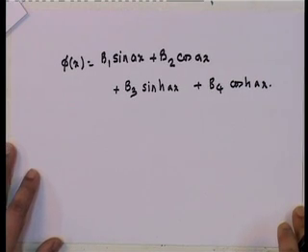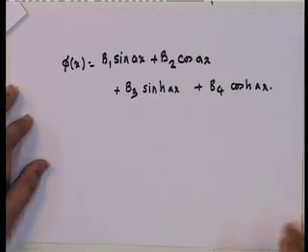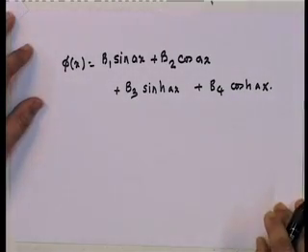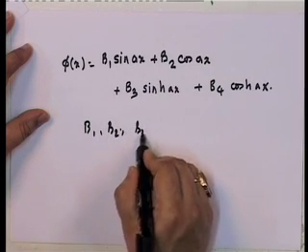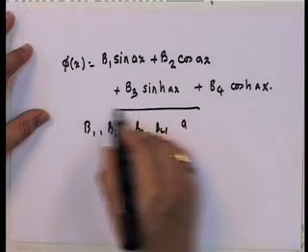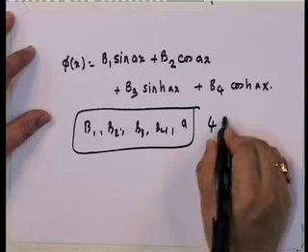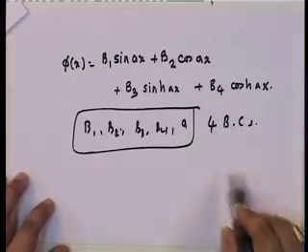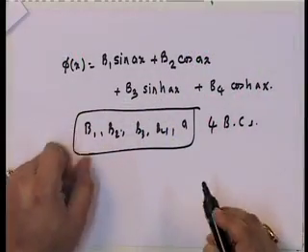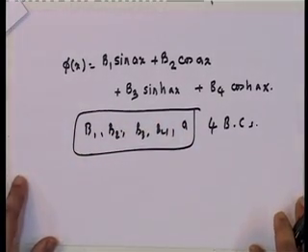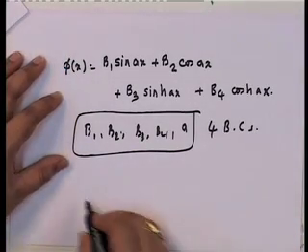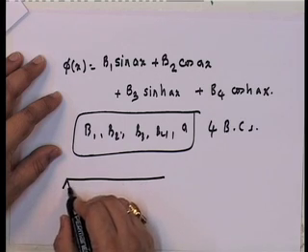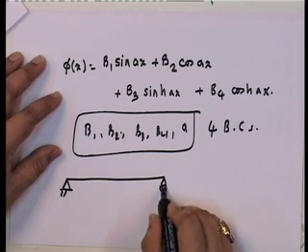So, now if you look at this, how do I get B1, B2, B3, B4 and A? Well, you have 4 boundary conditions, and with the 4 boundary conditions you can find 3 of these in terms of 1, and you can find the frequency equation, which gives A. This boundary condition depends on what kind of system. Let us take a basic simply supported beam.